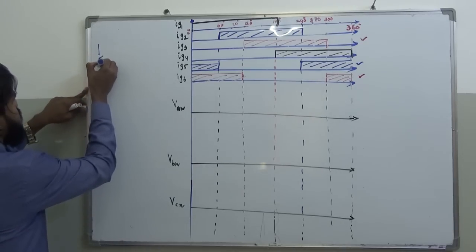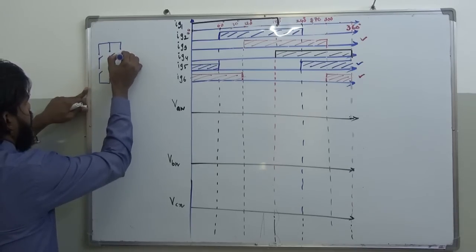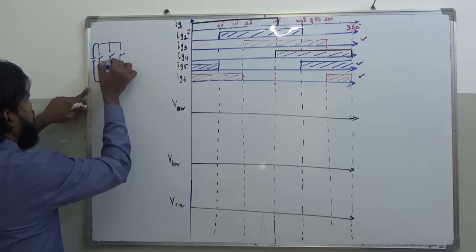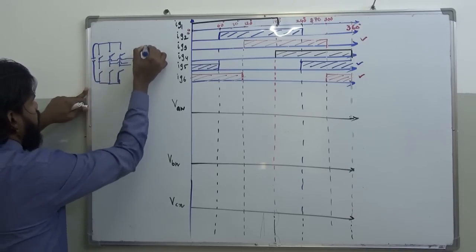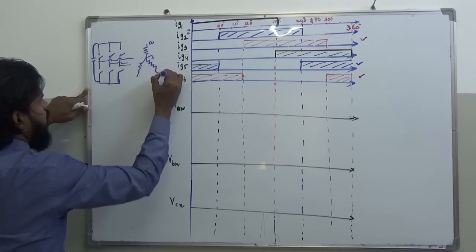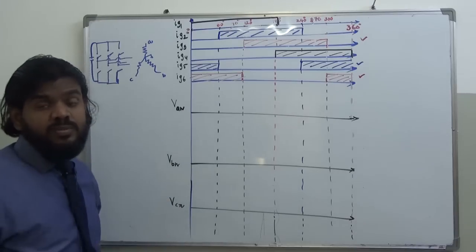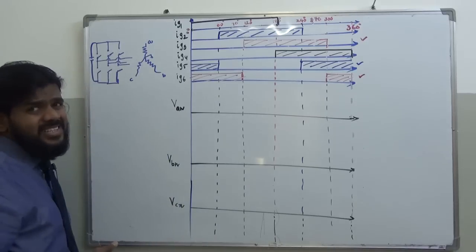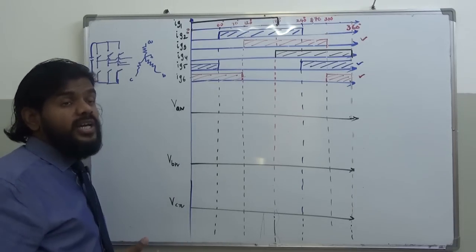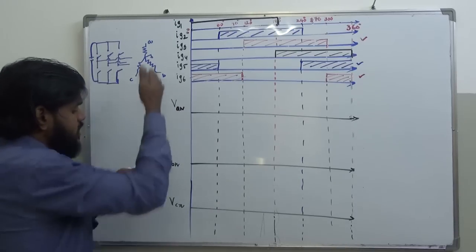So this is your switch. Supply. So this is the phases that are coming out. So this is the three-phase A, B and C. This is the load. Three-phase load may be a three-phase induction motor. So a three-phase induction motor has got a stator winding, which is a three-phase distributed winding, and each phase will have its own resistance. So I'm mentioning those resistances here. When I connect this inverter to control the speed of a three-phase induction motor, I got to connect this output of the VSI, voltage source inverter, to the three-phase winding of the stator of the induction motor. So the induction motor stator has got three-phase windings, and these resistances are the representation of that.